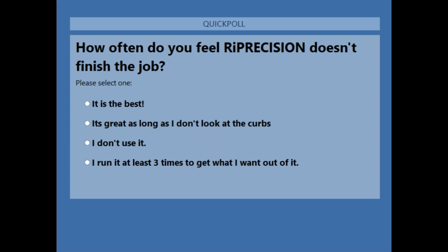Yeah, so the scan data adjustment report that I showed you is able to be created whether you manually create the tie points or use the automatic finding tool. So again, it's actually not called automatic finding tool. It's called Find Tie Objects Wizard. It's located under the toolbar in the second subsection of tools. There's a small gray line that defines them. And I'll show you all that in a second.